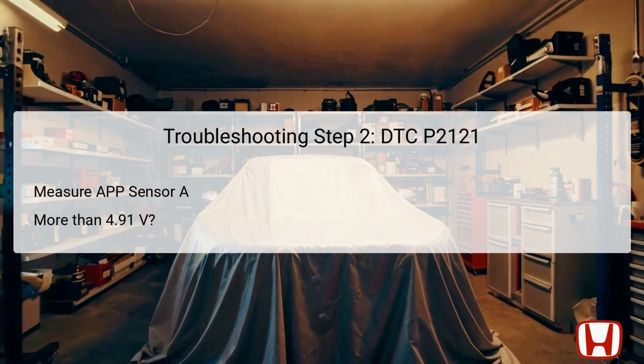In this second troubleshooting step, the technician again utilizes the HDS to measure the APP sensor A while the vehicle is in the on mode. The measurement is checked to ensure that the voltage does not exceed 4.91 volts. If it does, the technician can confirm a failure related to that specific reading. A yes response signifies that the failure occurred again, guiding the technician to step 8 for deeper analysis. If no, it leads to further investigation into intermittent failures that may indicate loose connections or faulty wiring, emphasizing the importance of checking physical connections for integrity.